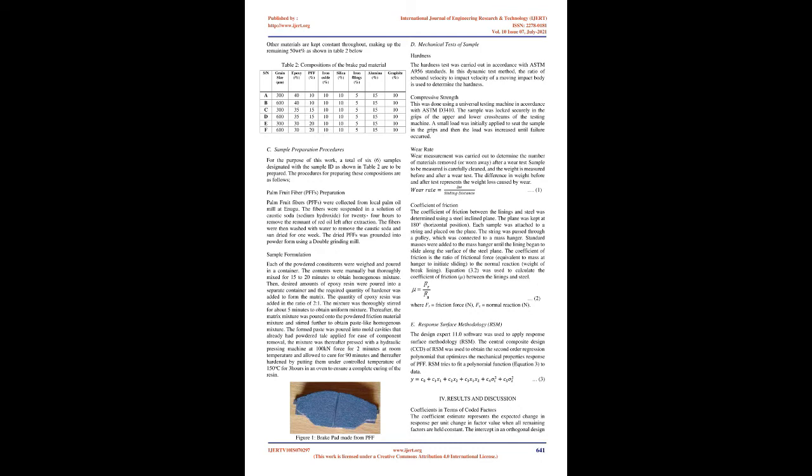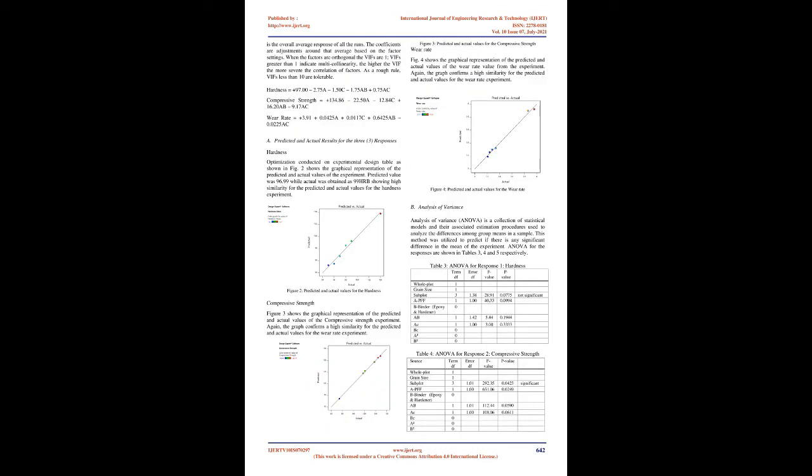The developed brake lining composites exhibited consistent coefficient of friction in the range of 0.35–0.4 and wear rates lower than 12 weight%. 3. Methodology. A. Material. The materials used during the course of this work are epoxy resin, palm kernel fiber, PFF, aluminum oxides, iron oxide, silica, graphite, metal chips, iron filings.